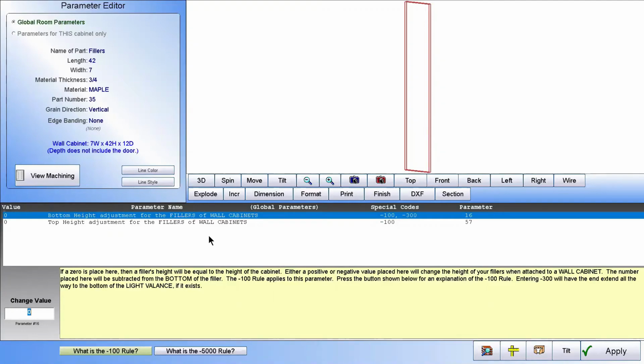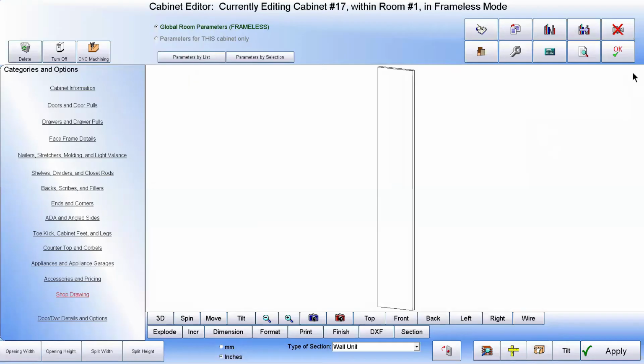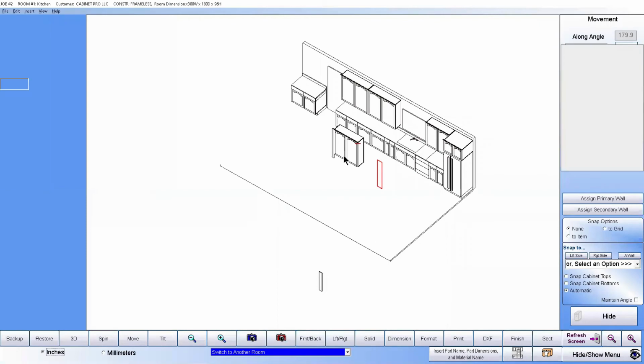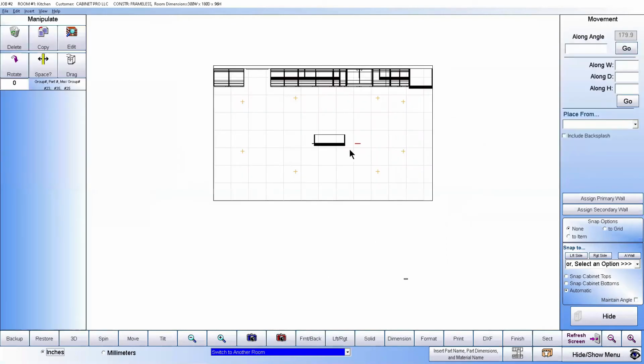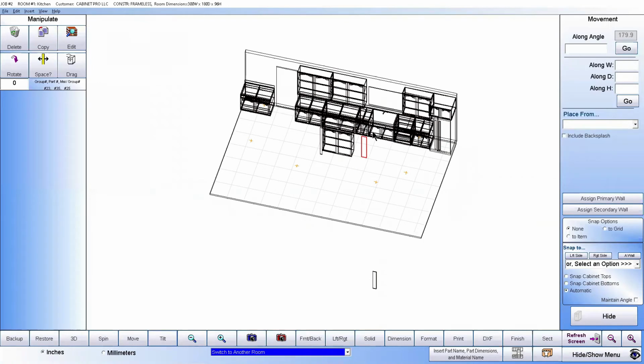At any rate, in a nutshell, the answer to your question, Cindy, is that you create a cabinet by itself, which is just a filler. And usually you want to make one for a base cabinet, wall cabinet, tall cabinet. You could make one just for one cabinet, and then just adjust the height and the depth based on what cabinet you're putting it on.